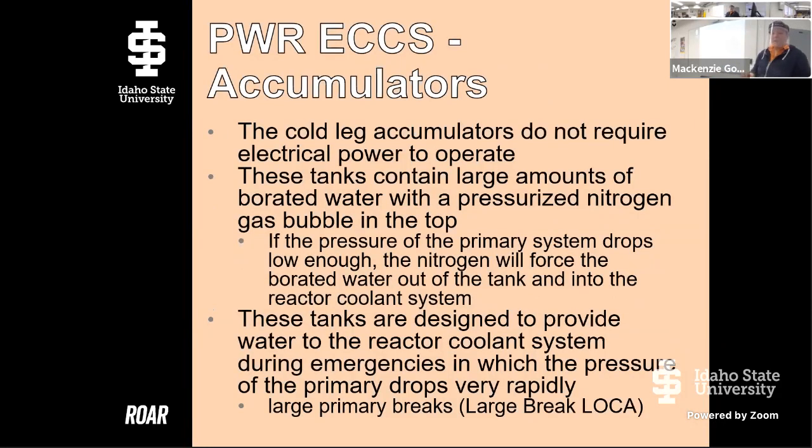And then the cold leg accumulators, they don't require any electrical power. They're just very large tanks. They have a pressurized nitrogen gas bubble at the top of them. And if the pressure in the primary system starts dropping, essentially that gas bubble just pushes the water in. One of the things that's a little bit backwards is you might think the high pressure injection system is for bigger accidents because it's going to be pressurized, it's going to create a lot of force. It's actually for the smaller LOCAs because the core can maintain its own pressure, and so it has to be at that highly pressurized same level that the core is in order to inject, right?